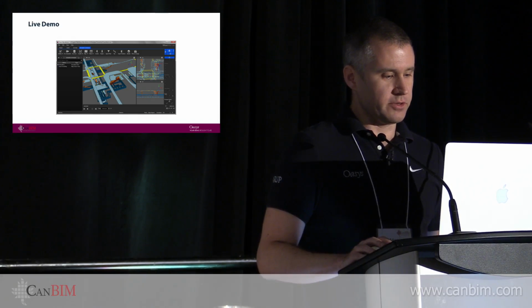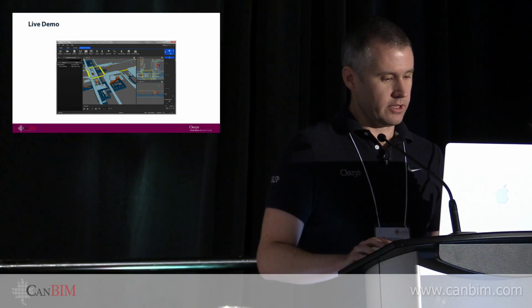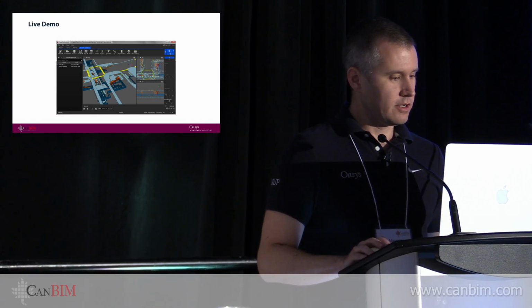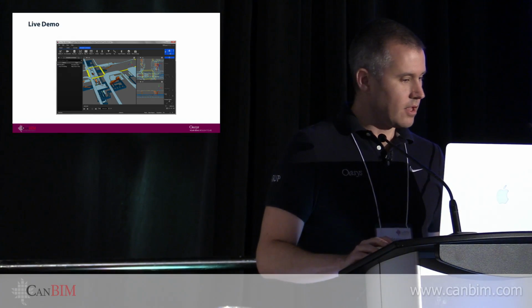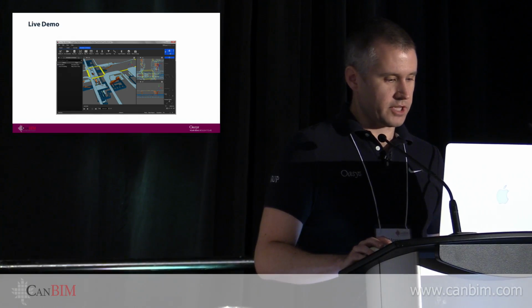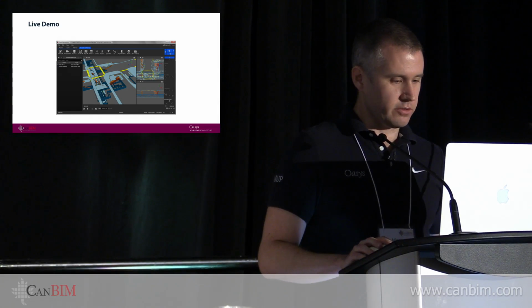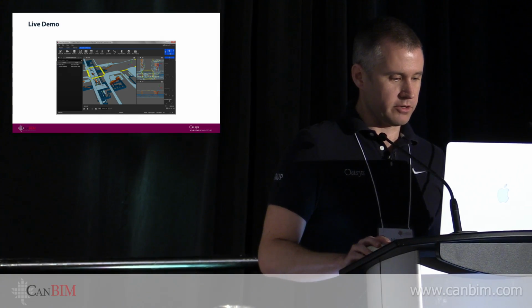And what Mass Motion is doing is going through this and reading not just the geometry, but also all the object properties that are associated with the IFC objects. So there it is in its raw state. And in the case where you're bringing geometry in from some other application, whether it's Revit or SketchUp or via an FBX file from somewhere else, what you can do is go around and say, these are walls, so I need those to be barriers.